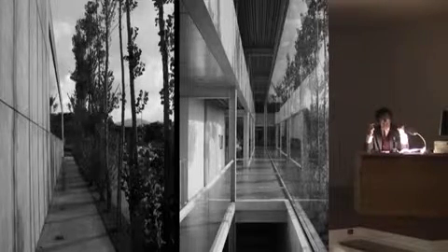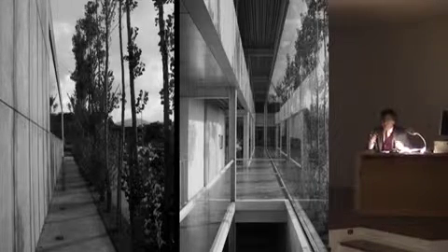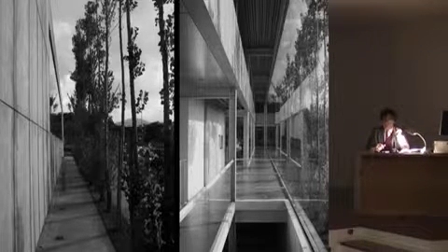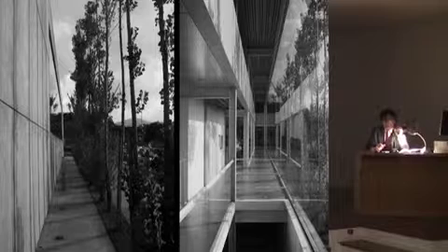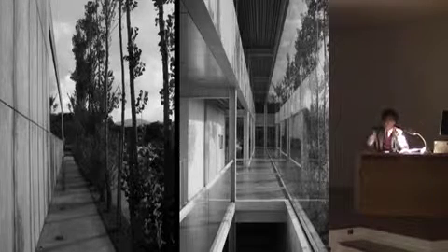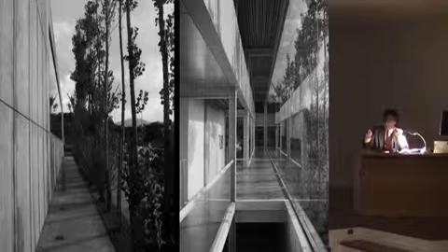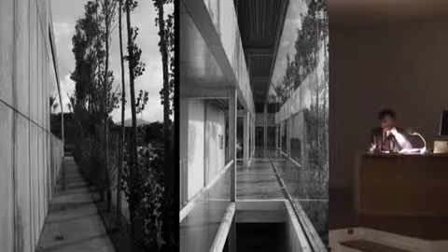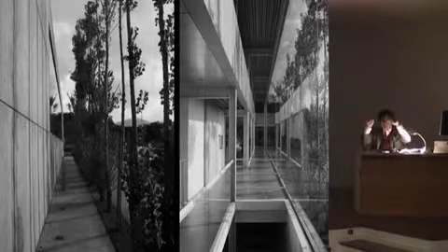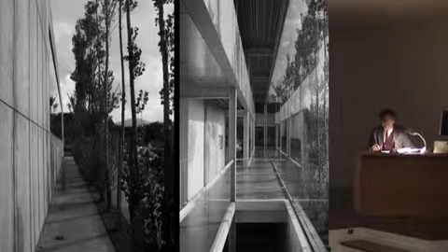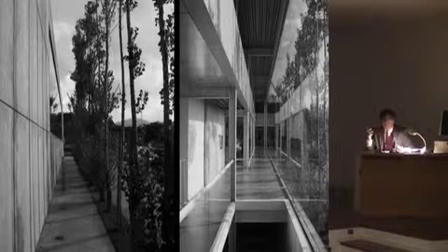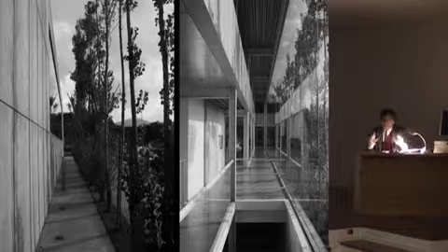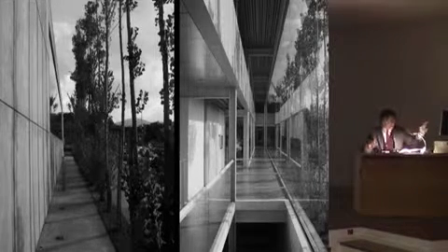Since there'll be condensation, because I didn't use Climalit here, because there's one thing: if you isolate a building very well, you will have weak points. It's very difficult. They just will be. And the condensation will affect those weak points, the carpentry or that joint or that material, and the condensation will be there because it will concentrate precisely on the weak point. Exterior dampness, different temperature, well, it just goes through the funnels wherever condensation finds them.